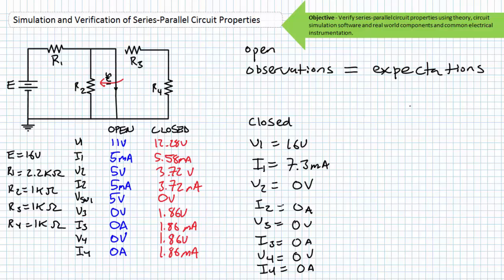If you observe too much current, it's because voltage is too high or resistance is too low. Shorted components remove elements from consideration. No voltage will be dropped across the shorted component. Because of the improper placement of switch 1 across R2, rather than making or breaking the connection with a series combination of R3 and R4, these resistors will not be connected to the original series circuit whether switch 1 is open or closed.